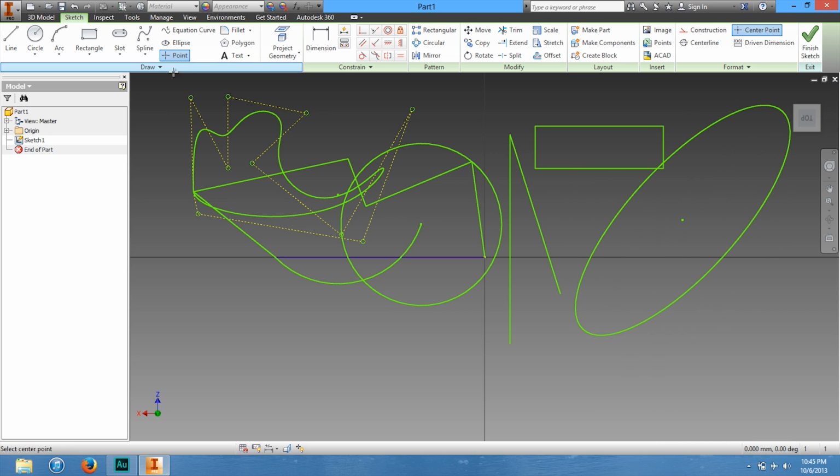And the point tool allows you to create snapping points for the 2D sketching. So if I wanted a line to snap onto the oval right over here, I'd click on this point right there, and then I go back to the line tool, and now I can snap right here where I put the point. And the fillet tool creates rounded edges on corners.